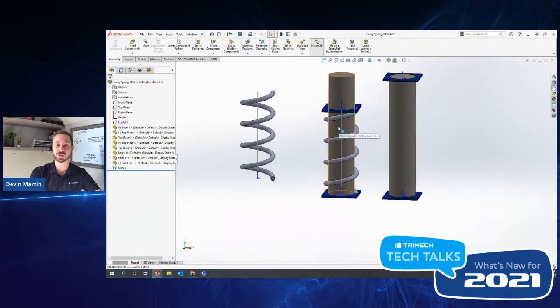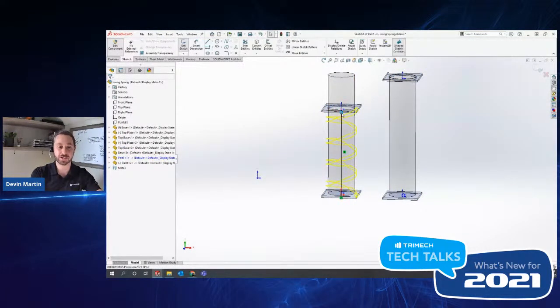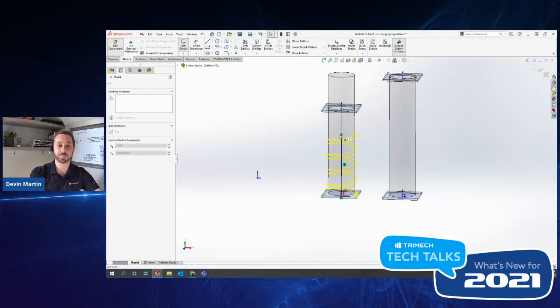So today, I want to also show a new little trick called flexible parts. It was in SOLIDWORKS 2020 and above, so 2021 as well. And we're going to be able to not only make this part living and flexible, but we can also have multiple versions of the same component in those different states. So I'm just going to go back to that part that I edited in context, and we're going to remove that relation that we've got there. So let's go ahead and delete our coincident.